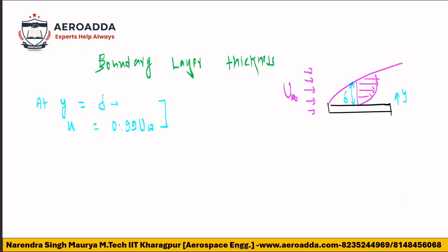Now, displacement thickness. Once the boundary layer is formed here, it is basically a dead region, where the velocity variation is very small and the velocity is very low because it is a very thin region close to the surface of the plate. So the total flow is actually shifted. Why is it shifted? Now I will show.